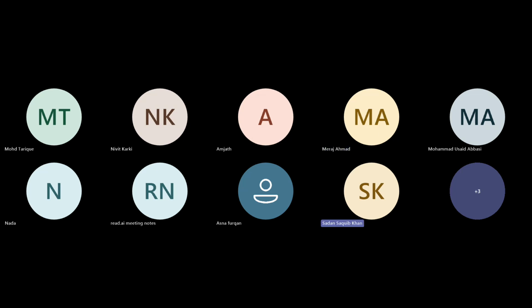One more question. Sir, is the test bench also synthesized? No, no. If you see in this design, we put all the files like top.v and datapath.v and the control path in the design sources. In simulation, we put test benches. If you put a test bench in design sources, it will not synthesize.